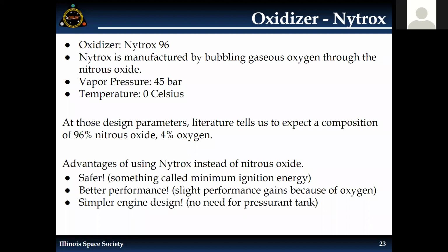I'll speak a little bit more on this in day 3 when we talk about ignition. But unless you're dealing with hypergolic fuels, which ignite spontaneously when they come into contact, most fuel and oxidizer combinations require a high energy threshold to cross in order to start reacting and trigger the chain reaction of combustion. So solid fuels are typically pretty safe when stored until you give them a spark or a pyrotechnic ignition. That's the reason they don't just spontaneously combust when they're mixed.